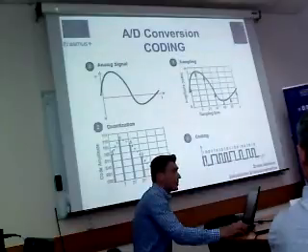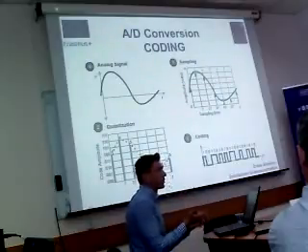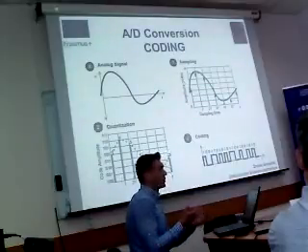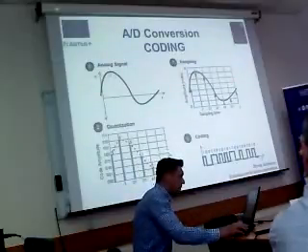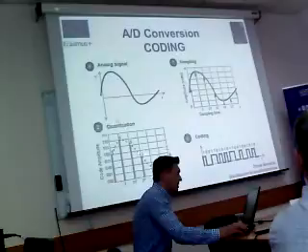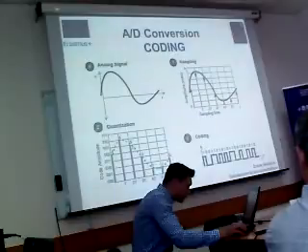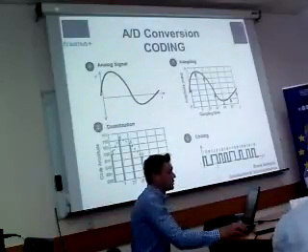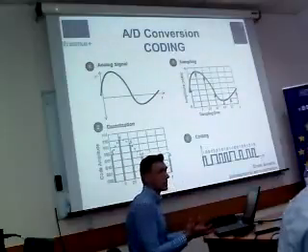For the time of the next conversion, because it goes there and it stays there, and the software developer who uses this analog digital converter can read it from this register as long as another sampling starts, another sample is taken, another quantization is done, and another code, for example 101, goes to the output register, and then it stays there for the time of another sample.